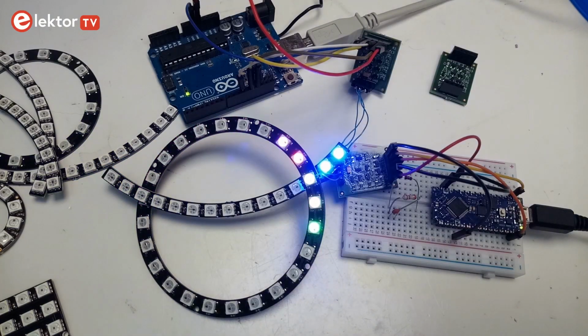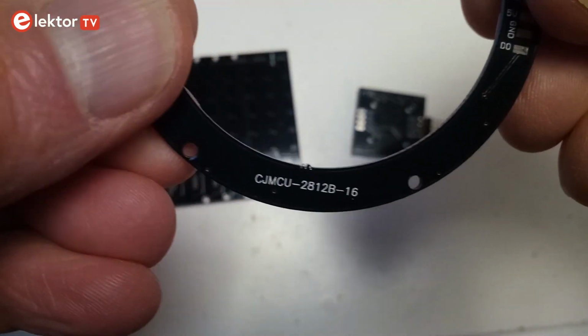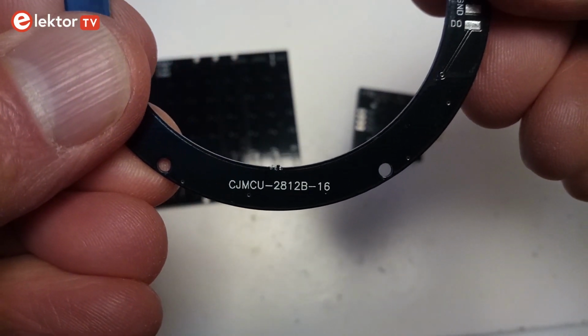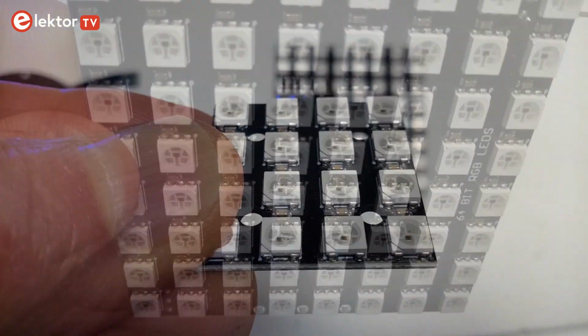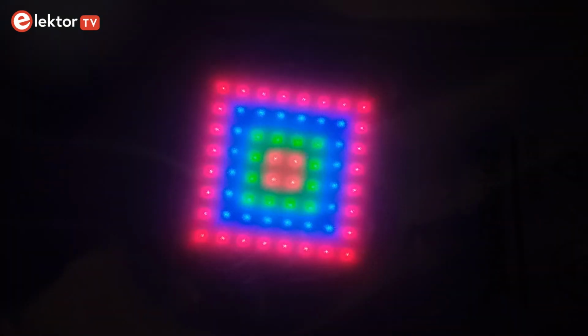I have tried this circuit with several types of addressable RGB LEDs and found it to work fine in all cases. Note that these LEDs are not all created, or should I say cloned, equal. I have strips labeled WS2812 and WS2812B and unmarked strips with 4-pin and 6-pin devices. It turned out that the unmarked strips were much more tolerant to timing issues than the WS2812 marked strips.